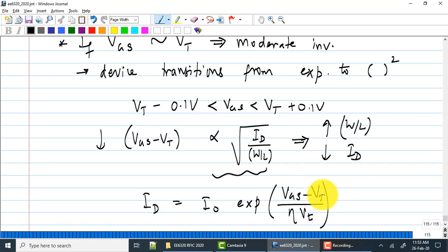If you keep going through the cycle, let us say you don't change the bias current, you only increase the width, you will not see any change in VGS minus VT. That's when you know that you're fully in subthreshold, fully in weak inversion. At that point, it will not be a strong function of the width at all. It will be a function of the current. Remember that VBE for a bipolar transistor is a function of the current. It is not a function of other things. And you will find the same thing here.